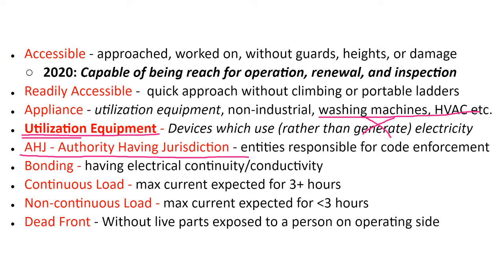Generally, code is going to defer to local jurisdiction authorities, which might have additional requirements above and beyond code. So code is a minimum safety threshold. In New York City, they might say, we're going to have more rigid conduit requirements in our 40-story tall buildings, because they're 40-story tall buildings. So we want to make sure that the buildings don't burn down. It's a heightened risk. So we're not going to include EMT conduit. We need rigid conduit. Local authorities have that ability. National Electric Code is not like a federal code.